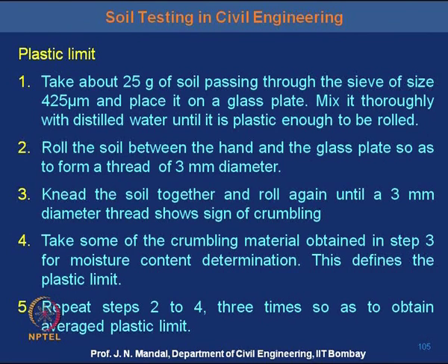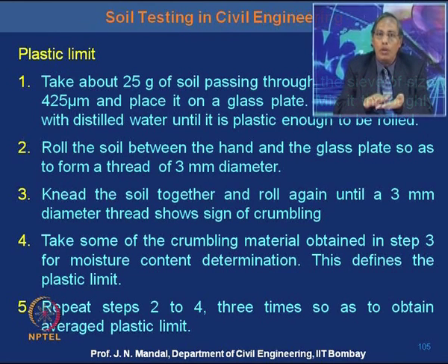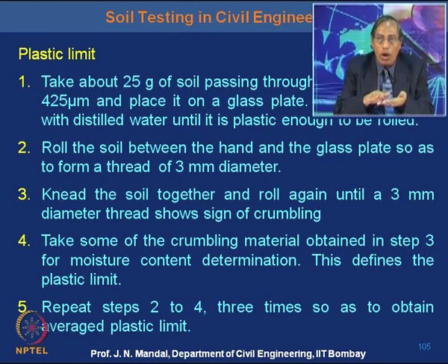Next, roll the soil between the hand and the glass plate to form a thread of about 3 millimeter diameter.